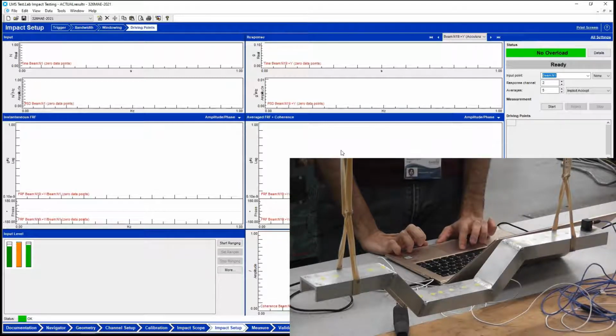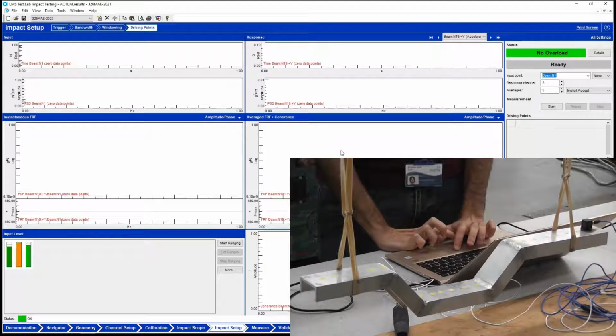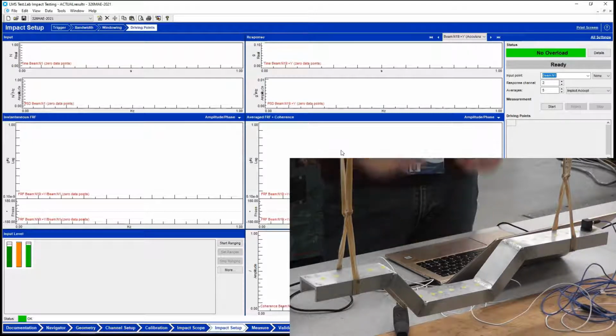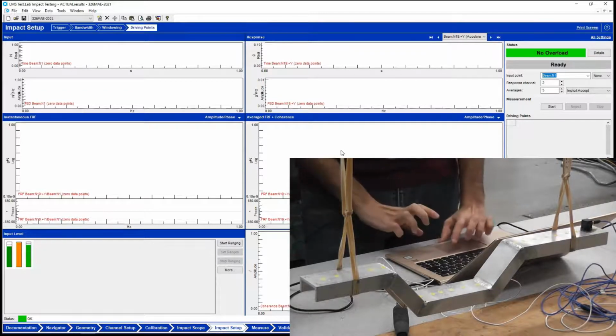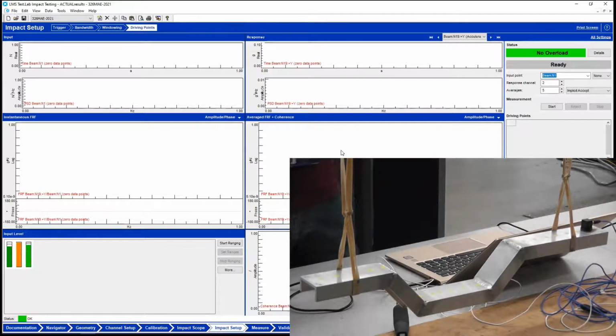This is very important because it lets us scale the mode shapes properly. Now, of course, this beam might bend, and you know that eigenvectors, the mode shapes of that beam, are the same up to a scale factor, so it doesn't matter if it bends by 1, or twice as much, or 3 times as much, or the other way, -1, -2, -3. That's the same mode of vibration.